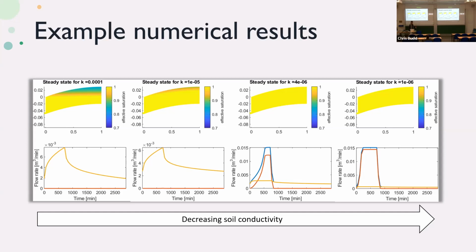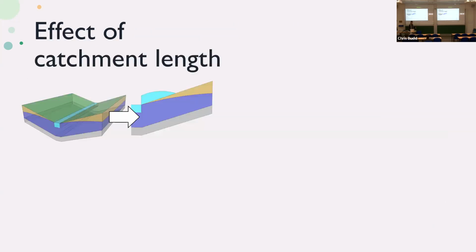And we can investigate the other parameters in a similar way and try to systematize it and get some scaling law, even numerically, from this model. Another interesting thing that we can learn from the reduction of the three-dimensional model into a two-dimensional model is that we should be able to write down that the flow coming to the river is the same in all the cross sections. So the total flow in the river should be proportional to the length of our river, to the length of our valley, as long as the flow in all the cross sections is identical.